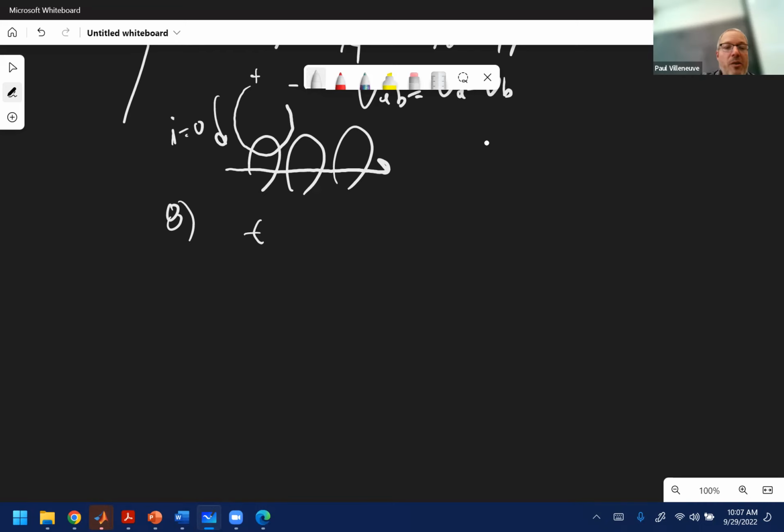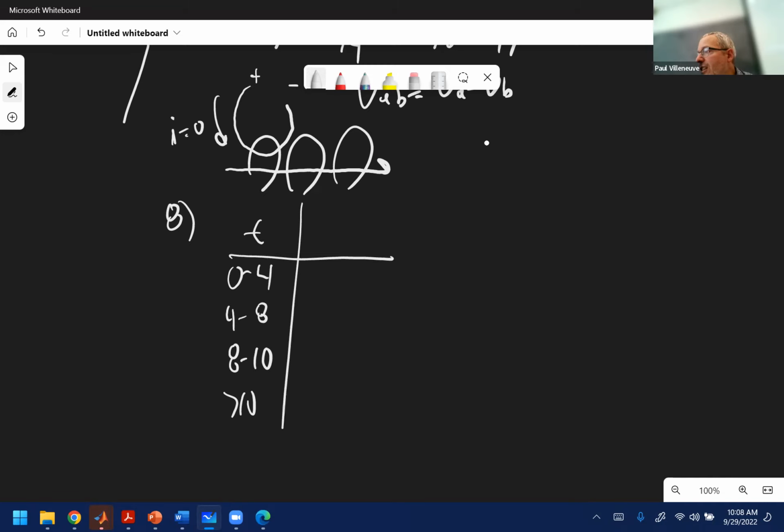The time we see from 0 to 4, it's a fixed constant slope. From 4 to 8, it's fixed. From 8 to 10, it's fixed, and anything beyond 10, it's 0, right? So the first thing it says is, all right, we have a 0.2 farad capacitor, and we're given the voltage here. So we know that v_C(t) equals C di/dt, right? So if we want to solve for i(t), wait a minute, let me fix my equation here.